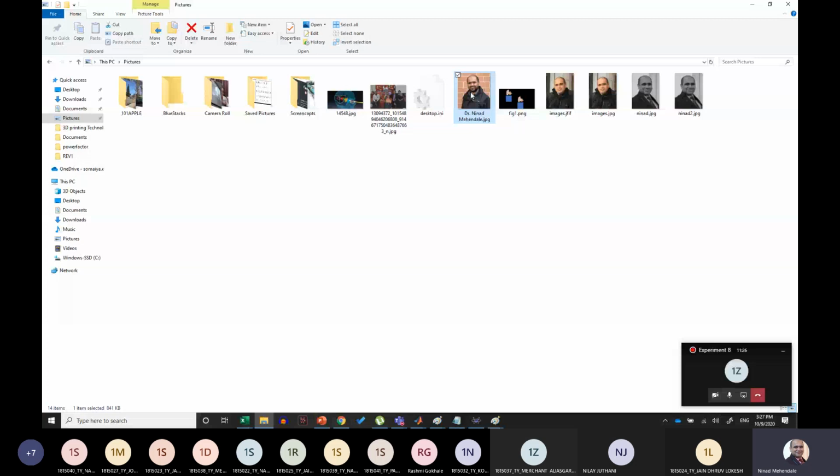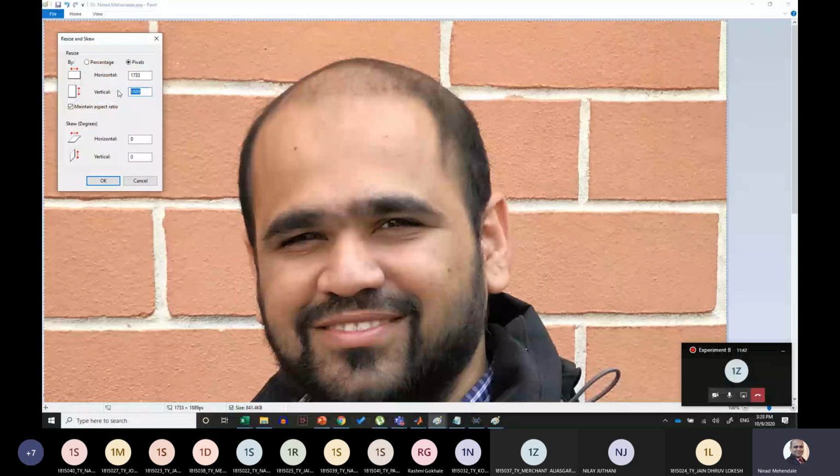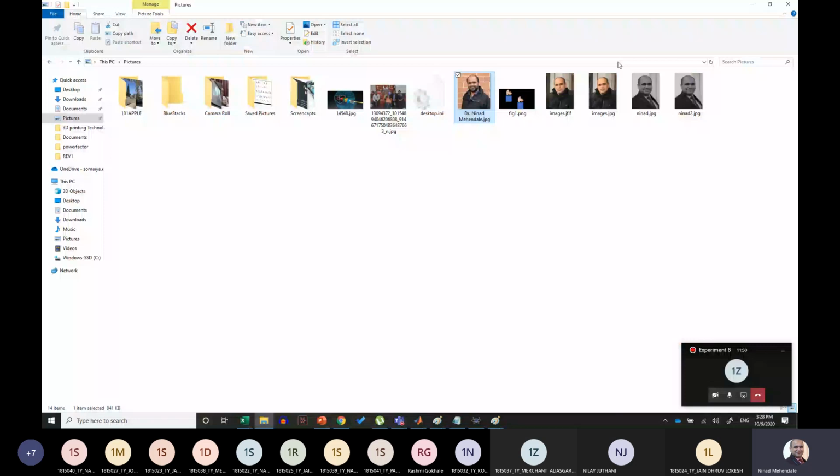Then you select all. Go to Home. Go to Resize and go to pixels. Now the bigger number you have to set to 720. Click OK. Then Control C to copy this particular picture. Come back to the Lab Center logo and paste this. And then file save. Now if you run your simulation, you should see the updated picture on this particular TFT screen.